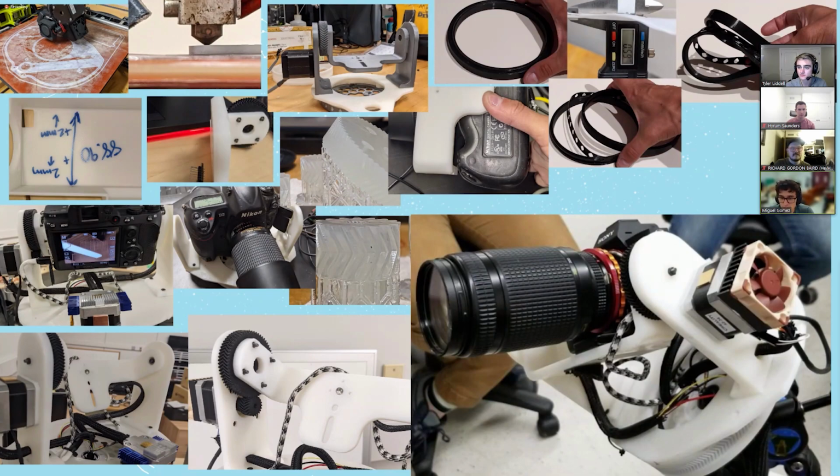On the bottom here, you can see the whole system together. And this mount, in order for it to be able to track stars, we wanted to make sure that it would be aligned to the North Pole. And then also, we wanted to have it so that it was only a single degree of freedom while we were moving. So in order for that to work out, we would align them out. And from there, we just decide what the declination angle is. And then we only have to worry about the 15 degree per hour drift. So using the TMC 2209 motor drivers, which have a 256-step interpolator in it, that allowed us to get to that 15 degree per hour drift.